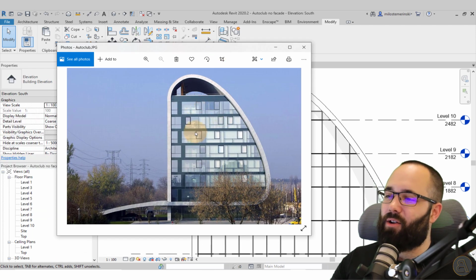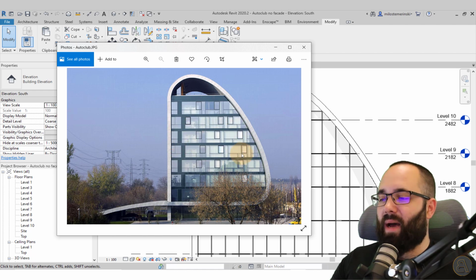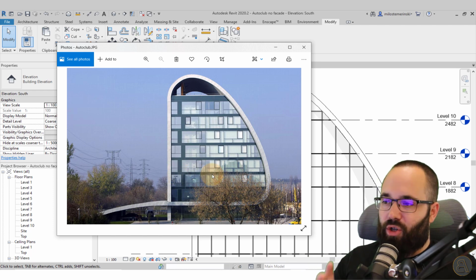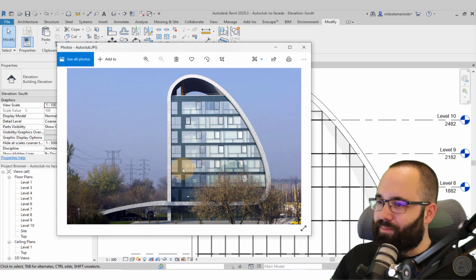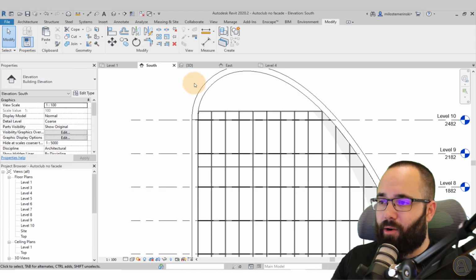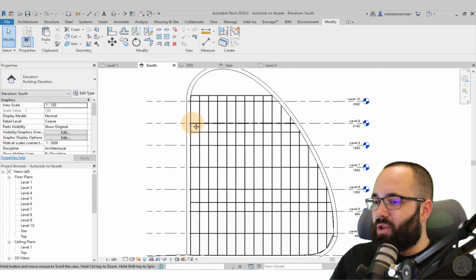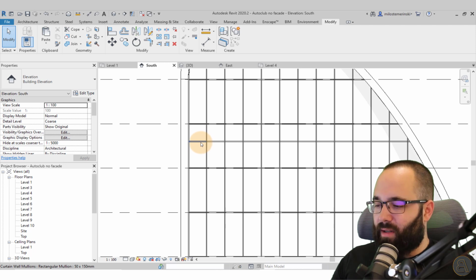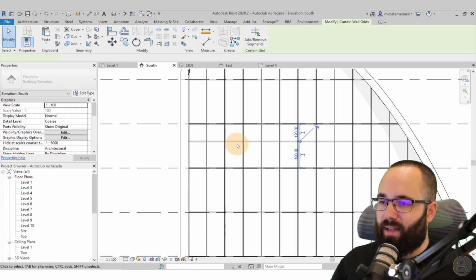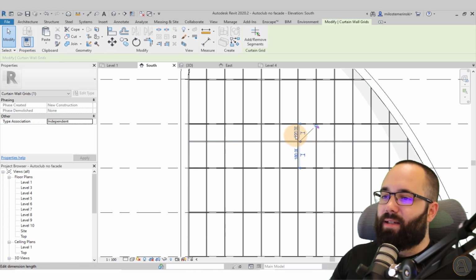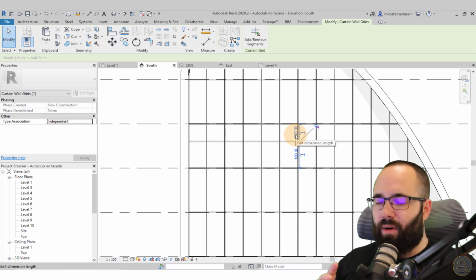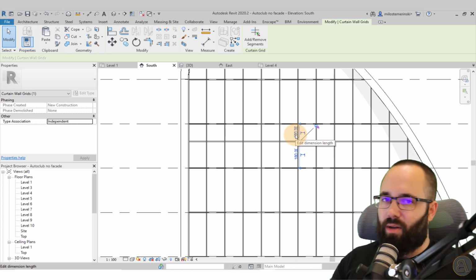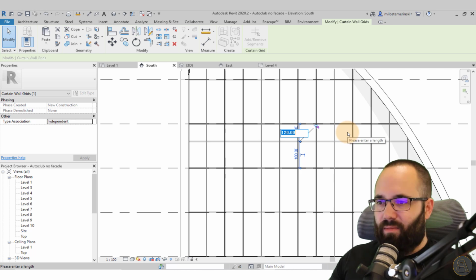So you can see here, the floors are obviously here, and then we have these blue panels that are showing us where the floors are, basically masking the construction part of that floor. So we want to have that here. For that, we can say, okay, here we have this extra grid. I'm just going to use the tab key a few times to select the grid itself. And then I can say, okay, the thickness of the floor plus the construction and all of that, let's say it's 40 centimeters.